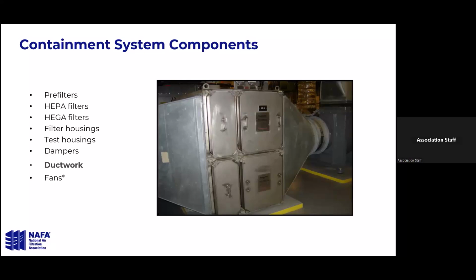You'll generally have dampers, which will be bubble tight dampers that can be closed for either decon of the housing if it's in a biological application, or just for filter change out and safety. From that standpoint, you can make sure that housing is shut down completely before you do those things.